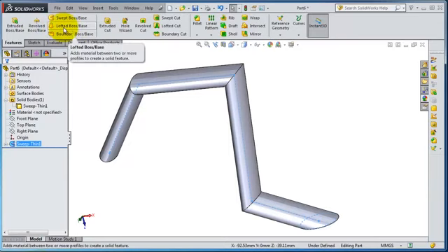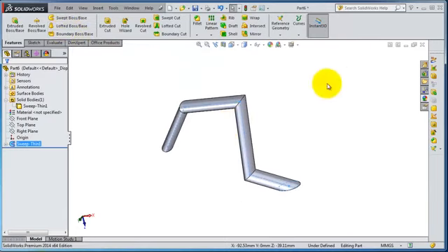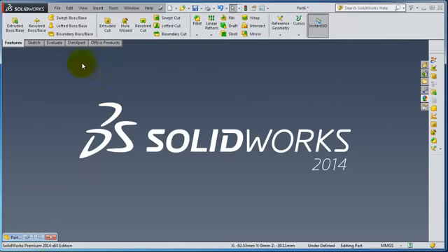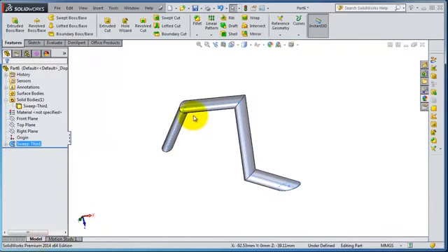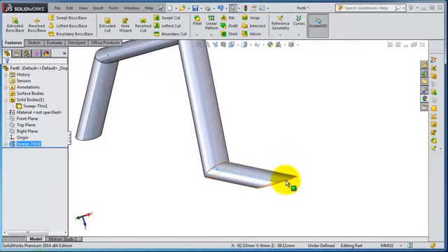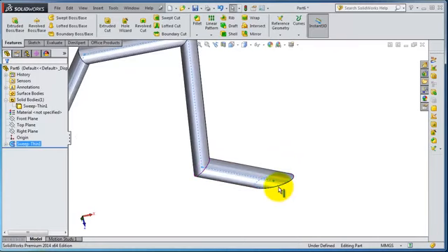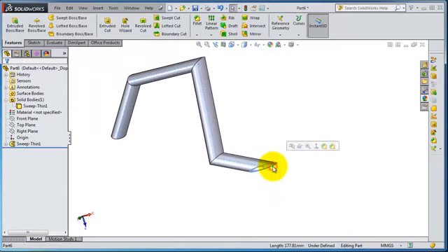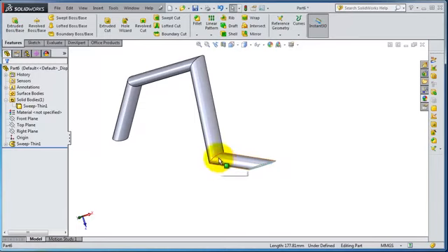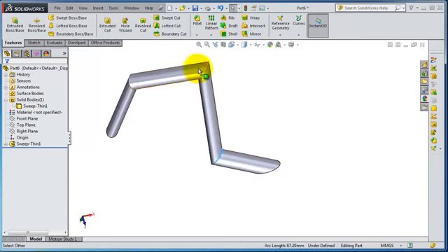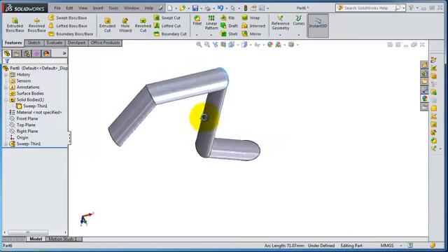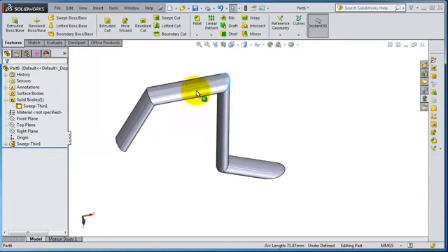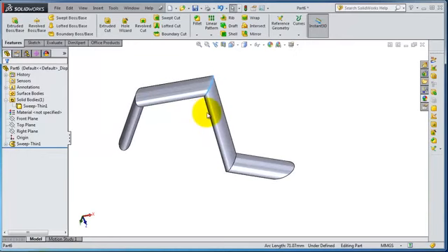feature, the lofted post. So for creating lofted posts, we need to have different sketches on different planes, so that we are able to loft between them. For example, you can imagine this part, this sketch is on that plane, and that edge on a different plane, and that is on a different plane. So that means we need to insert planes. So in this tutorial, we're going to talk about inserting planes.